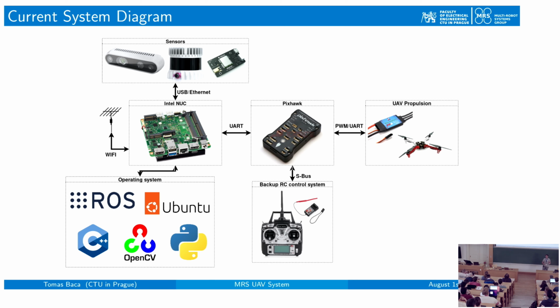And it can give commands to an underlying embedded hardware, which handles the fast feedback which is needed for the attitude and attitude rate control of a drone. This board here is Pixhawk. It's the most used, and one of many platforms which can support the hardware of the drone with software for stabilization and control.